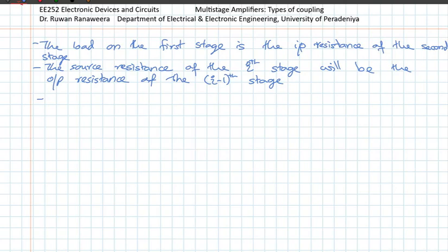What matters is that if you have a very high input impedance Ri1 as the first stage, like in the common collector amplifier, and a very low output impedance stage as the last or nth stage, like the common collector amplifier again, then you can acquire the high gain through multiple stages in between.